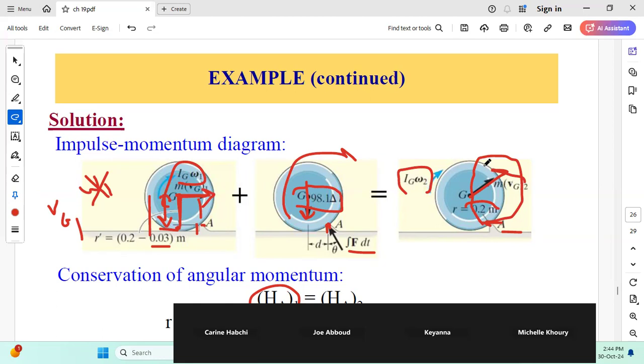We'll do this in steps, but now forget the work about potential energy. Let us stay in collision. In collision, what will happen? You will transform your motion from general plane motion to rotation about a fixed point. Okay, so because now you are rotating about a fixed point, just after collision, what will be your velocity?